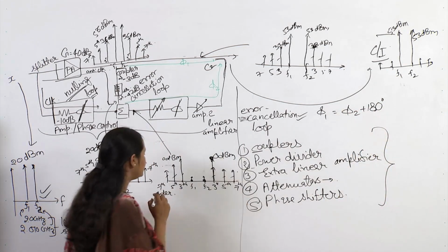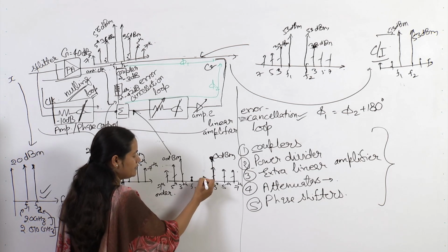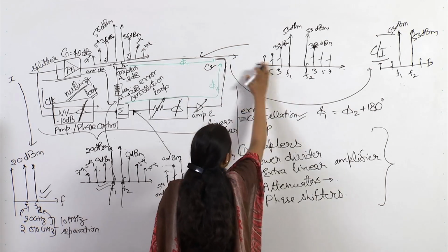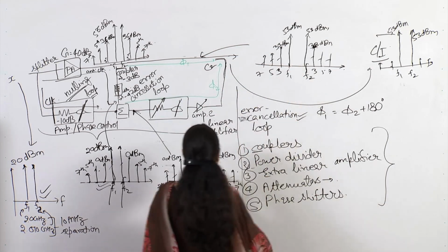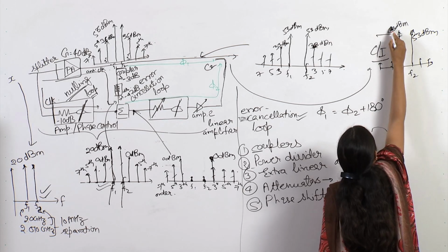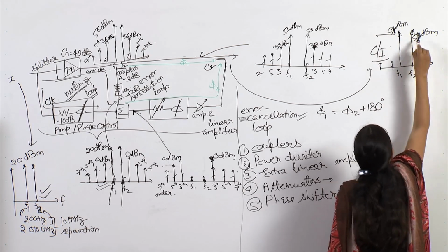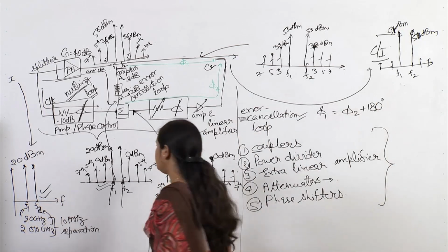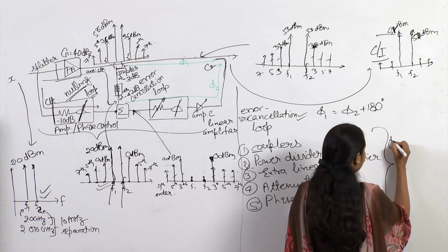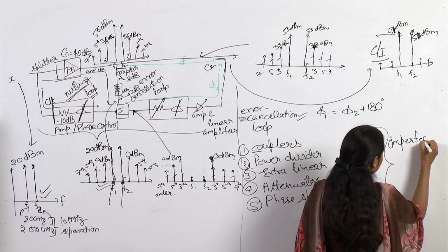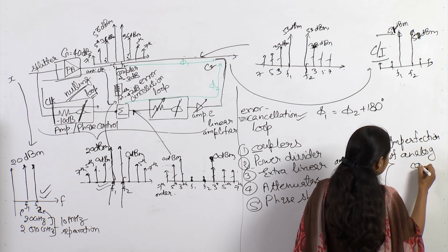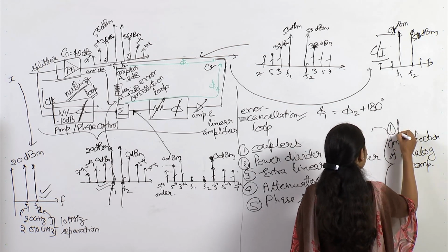Moreover, in the first path, if you had some tones remaining here and this tone will go here and add with 180 degree with the signal which is coming from the other path, then because they are matching at 180 degree, this power will drop because it will be subtracted from there. So, maybe you will get only 51 dBm. So, you are losing 2 dBm gain in the main power. So, imperfection of these components is one of the hindrance. Then first limitation.